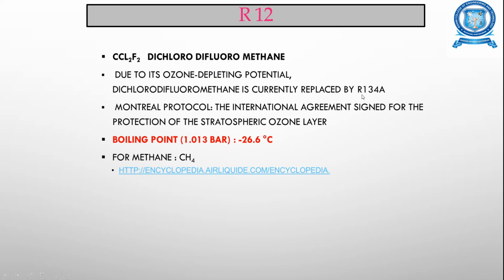Because of its ozone depleting potential, it is currently replaced by R134A, and the Montreal Protocol is the international agreement signed for the protection of the stratospheric ozone layer. The boiling point is minus 26.6 degrees Celsius.